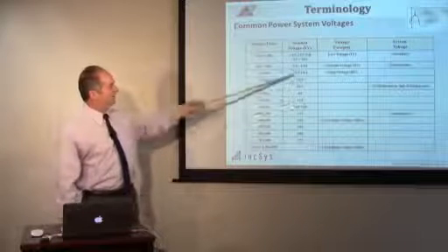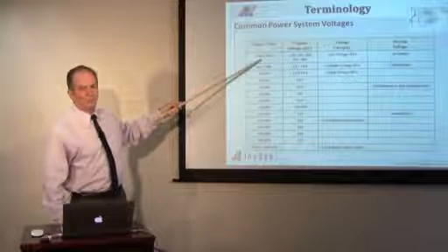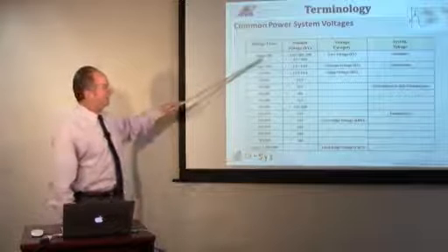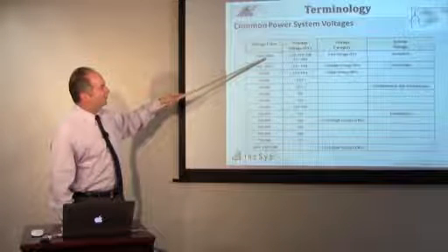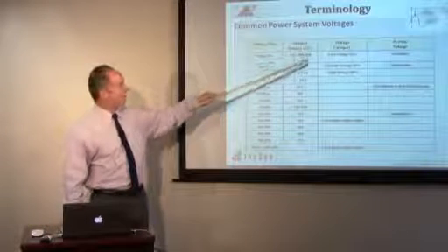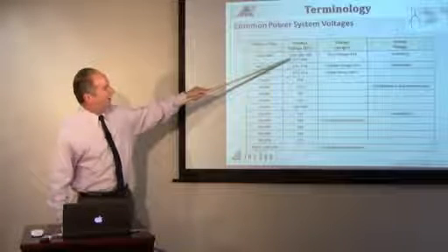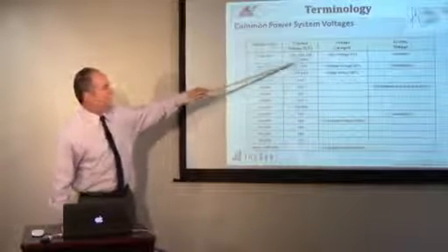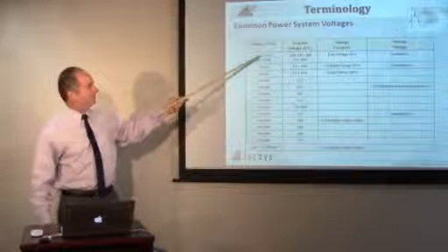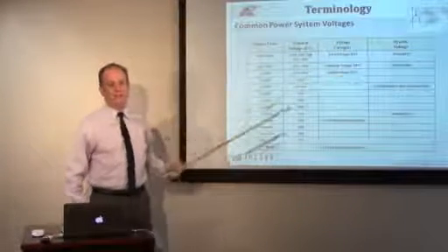Okay, then the voltage range, or the nominal voltages that actually fall in those classes, under 600 volts. 600 volts is customer service voltage, residential voltage, and this voltage would be any of our outlets. Since everything's measured in kV here, we're talking 120 volts, which is 0.120 because it's kV. 120, 240, 208, 277, 480. Those are voltages that fall under that 600 volt class. We'll talk about all those later. That's considered low voltage. It's also considered secondary voltage.